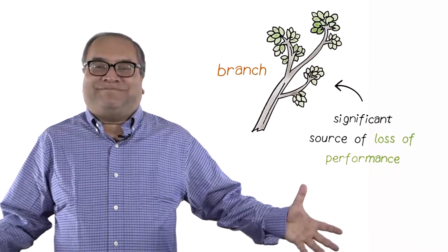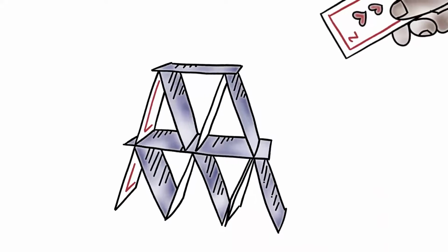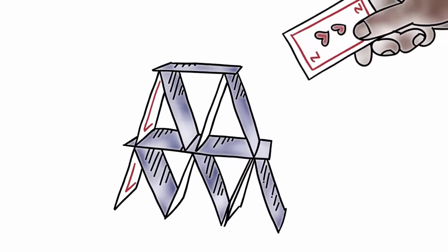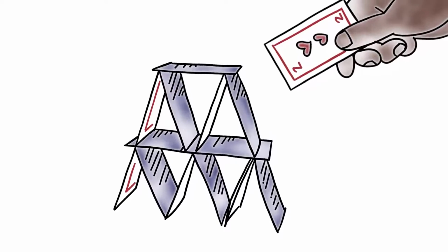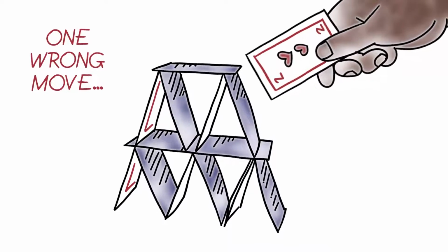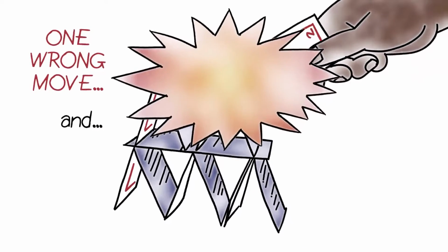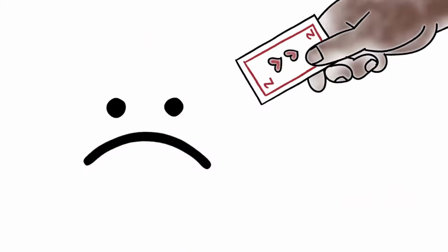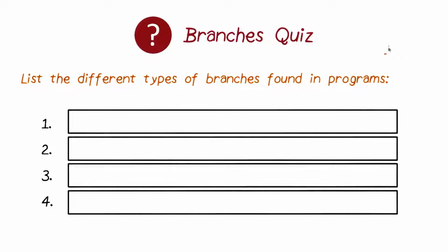and affects the design. We know that branches can have a great effect on the efficiency of execution of a program. Imagine the effect of branches on VLIW architecture for a minute. One wrong move and you may have to throw away not one but multiple instructions, and all the gains that you had could be compromised. So students, the last aspect of microarchitectures that is really important for embedded systems in particular is branches.